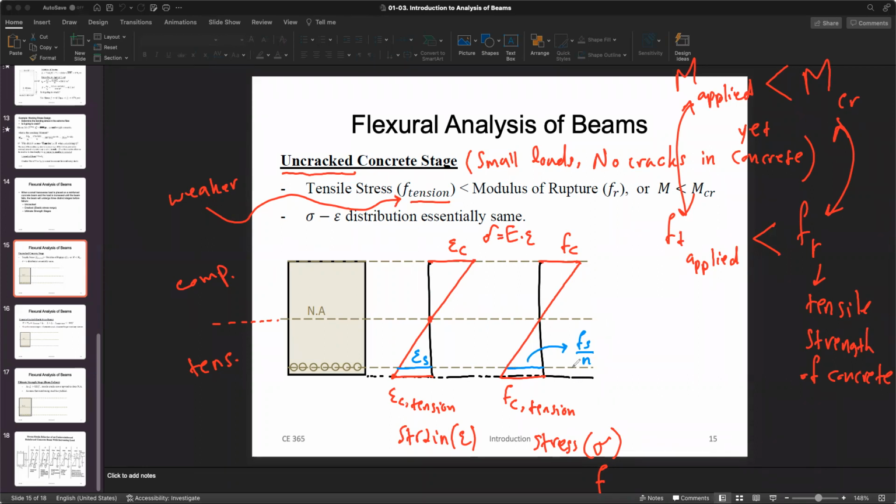So at this point, we know that we have a tensile stress in steel. In a way, we also have concrete at that level. If you think about it, there is a tension in the steel at this level, right? We need to use the modular ratio because you're changing material. Also, we can say this plane is like concrete at that level. The stress in concrete also has a stress at that level, which is equal, right, at this S level. So from both aspects of looking at the steel or concrete, we can talk about this particular level.